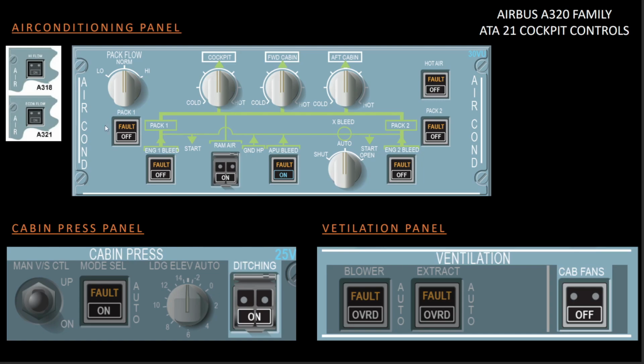And I told you that there are three scenarios when we have to discuss the closure, that is manual closure, pneumatic closure, and automatic electrical closure. So manual closure is always via the push button, you set it off, the valve closes. Pneumatic closure, that is when you don't have enough upstream pressure. So this is an electrically controlled, pneumatically operated flow control valve. So when you don't have upstream pressure, the valve will not open.